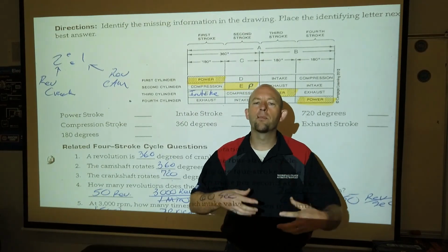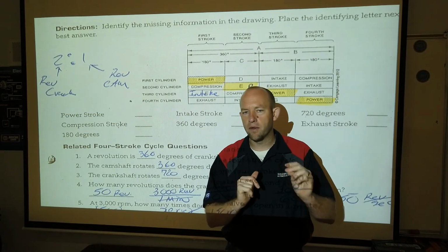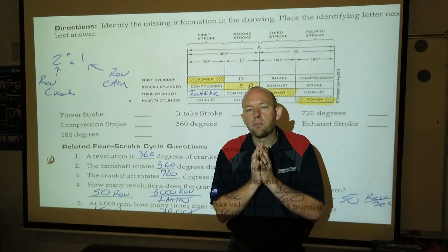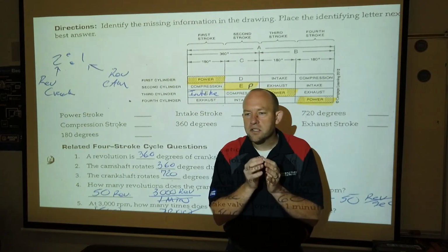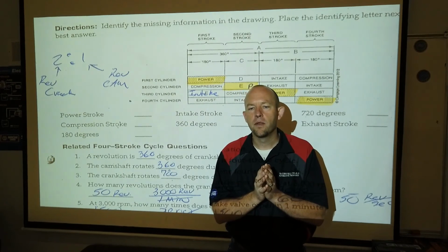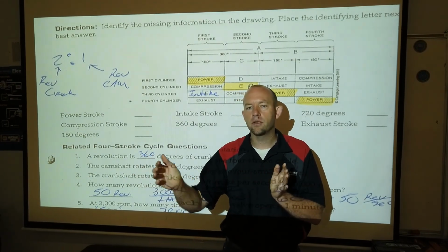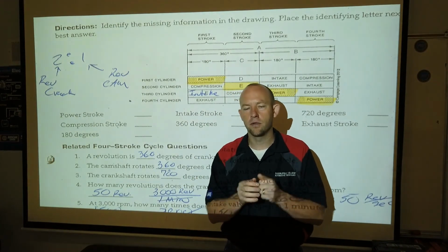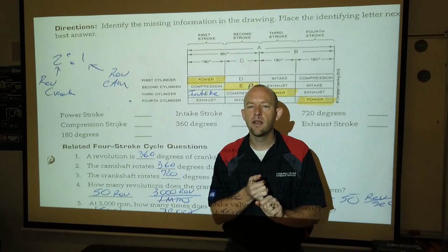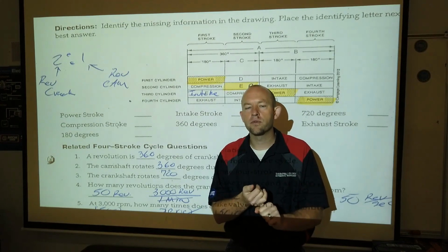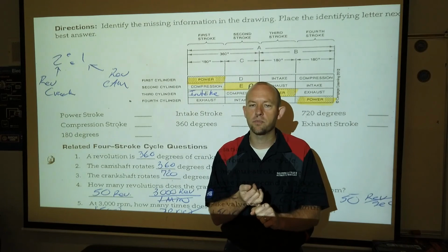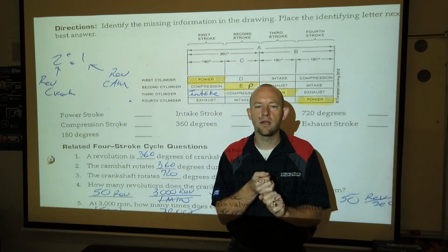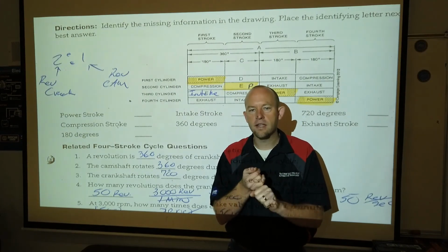So when you learn to appreciate how quickly everything has to happen with these engines, then it becomes pretty easy to understand how some seemingly minor problem starts to become a major drivability issue or major running problem. Say it didn't fire number one cylinder. Boom, you feel it, because we need 25 power strokes a second per cylinder, 25 sparks per second per cylinder at just 3,000 RPMs. That's 50 sparks per second per cylinder at 6,000 RPMs.